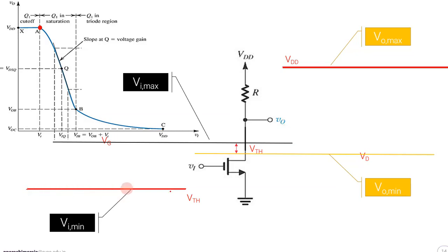Now for this, what is the corresponding output that you can expect? How will I read from this graph? Just draw a straight line that would intersect here, and you can read out your Y value in order to get the output, because this is my output axis right now. Okay, this is a VTC graph. Do not get confused with the previous graph where we had the output on our x-axis, and right now we have the output on our y-axis. You can see that this red mark corresponds to an output value equal to VDD, and that is what is marked over here.